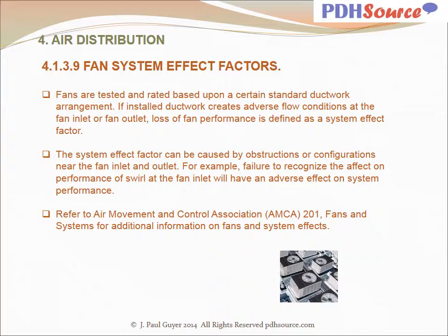Fan system effect factors. Fans are tested and rated based upon a certain standard ductwork arrangement. If installed ductwork creates adverse flow conditions at the fan inlet or fan outlet, loss of fan performance is defined as a system effect factor. The system effect factor can be caused by obstructions or configurations near the fan inlet and outlet. For example, failure to recognize the effect of swirl at the fan inlet on performance will have an adverse effect on system performance. Refer to Air Movement and Control Association, AMCA, Standard 201, Fans and Systems, for additional information on fans and system effects.